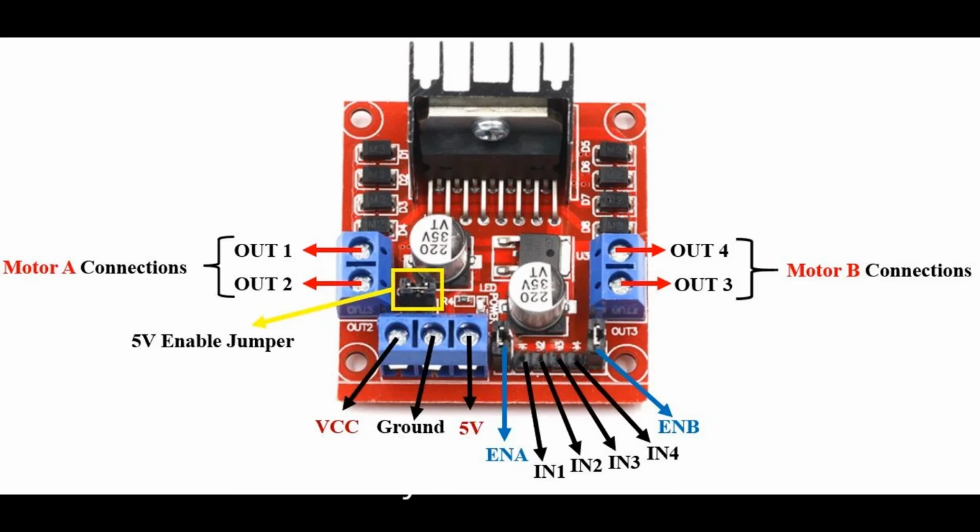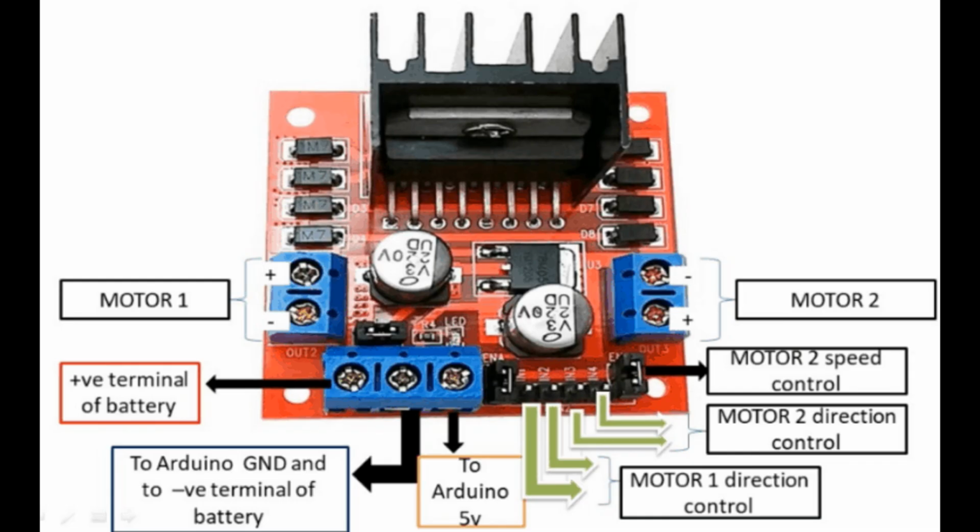4. Key features of VFDs. Speed control. The primary function of VFDs is controlling the speed of the motor. Speed can be adjusted smoothly from 0 to the motor's rated speed, allowing for more efficient operation and flexibility. Torque control. Some VFDs can precisely control the motor's torque, making them suitable for applications where torque stability is critical. Soft start/stop. VFDs provide a smooth ramp-up and ramp-down of motor speed, preventing mechanical shock, reducing wear, and preventing excessive current draw during startup.